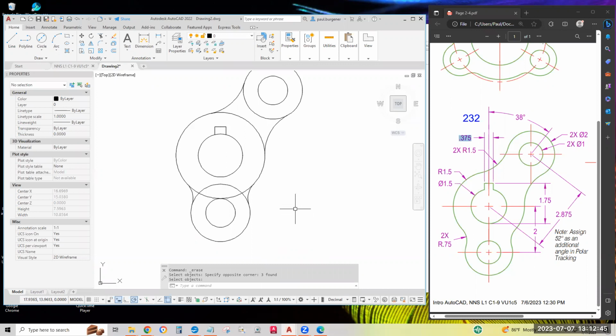Now, I believe for cutting edges, if we select just this circle and all 4 of the filleted arcs, we can quickly trim away everything and save a lot of clicks by minimizing the cutting edges. Click trim. And rather than having everything as a cutting edge, which is usually beneficial, let's select just the 3 things I named. Select cutting edges. I want this circle to be a cutting edge and all 4 of these arcs to be cutting edges. Hit enter.